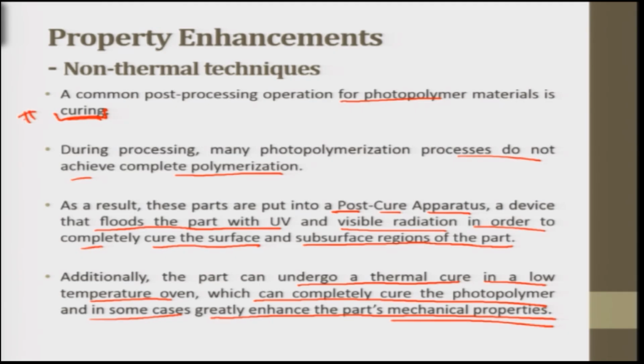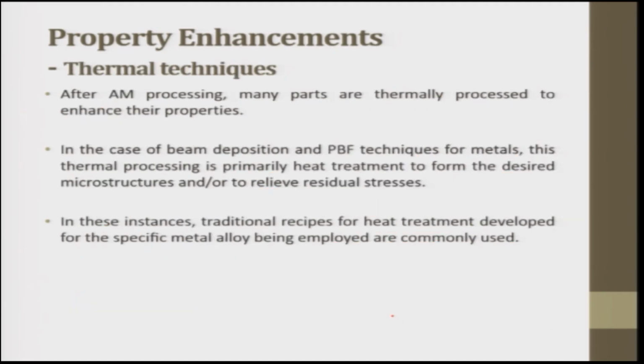This is important. So there are certain thermal techniques as well. After additive manufacturing processing, many parts are thermally processed to enhance their properties. In the case of beam deposition and powder bed fusion techniques, for metals, this thermal processing is primarily heat treatment that is there to form the desired microstructures and to relieve the residual stresses.